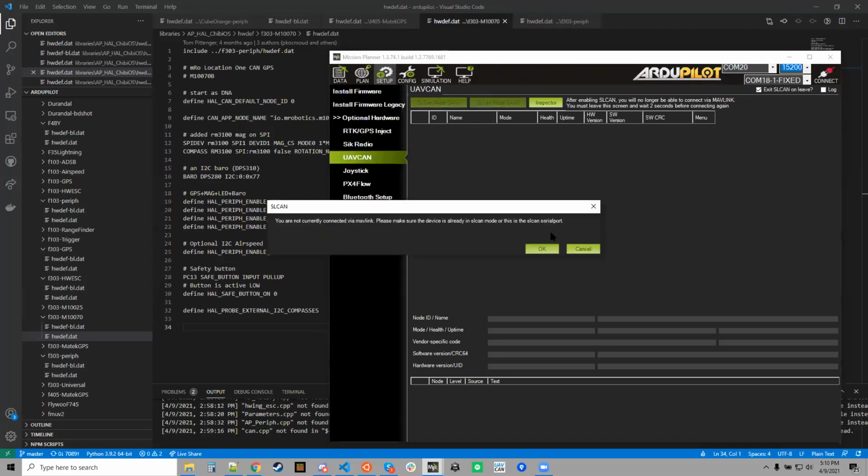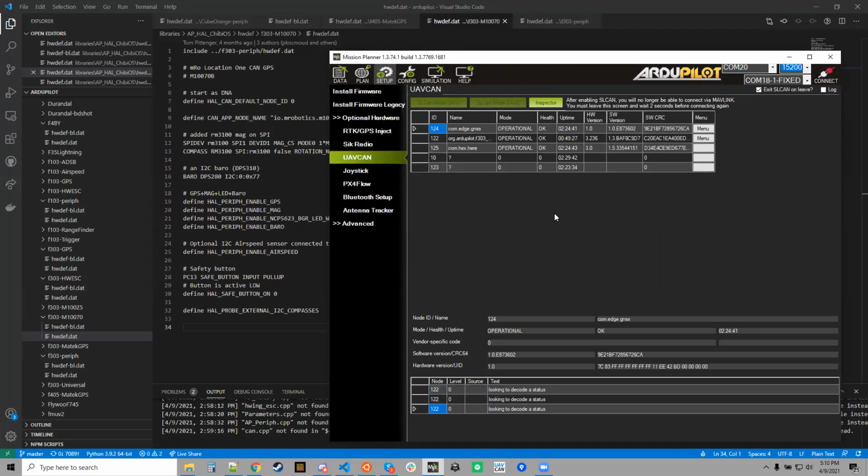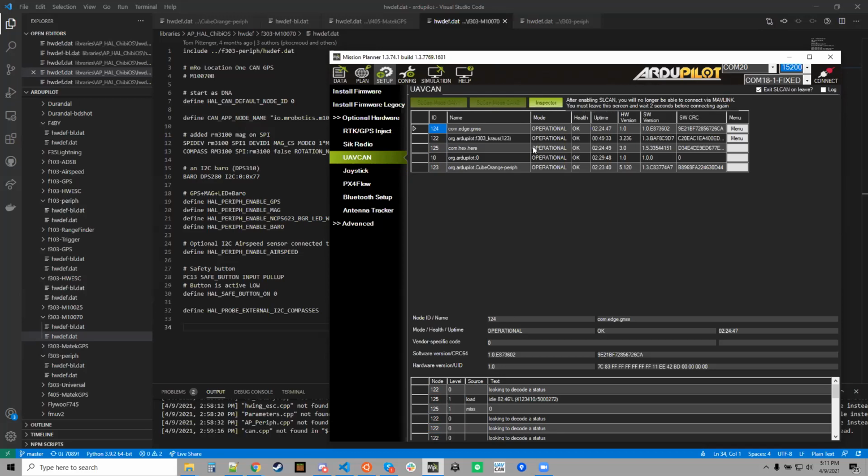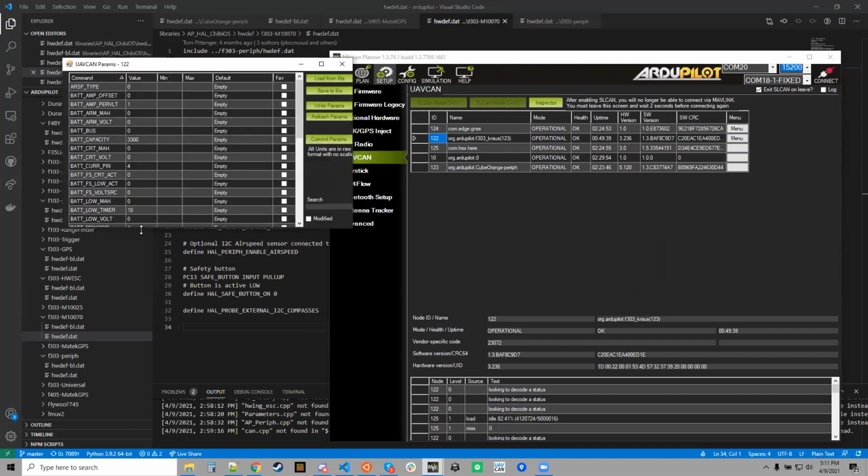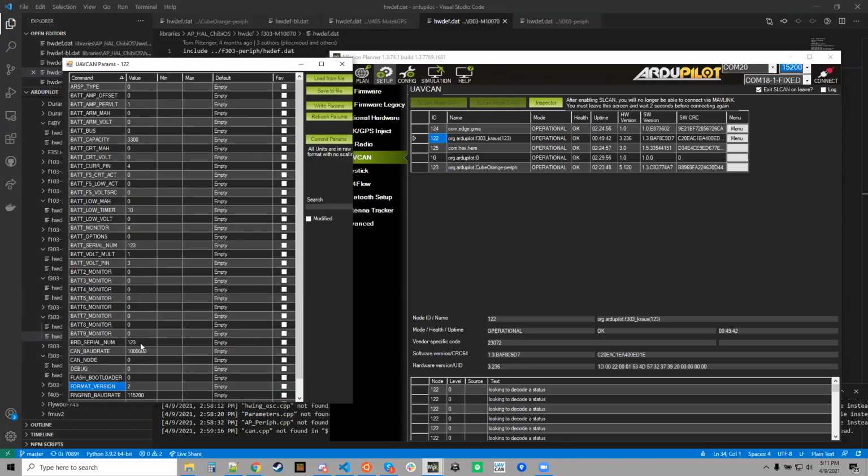Yeah. And SID has been working on patches to make it easier to assign the GPS node IDs to a particular GPS ordering in our GPS library to make that position assignment easier, because at the moment it is quite tricky to get that right. Basically because the CAN nodes can come up in any order. We can't control what order they appear on the bus.